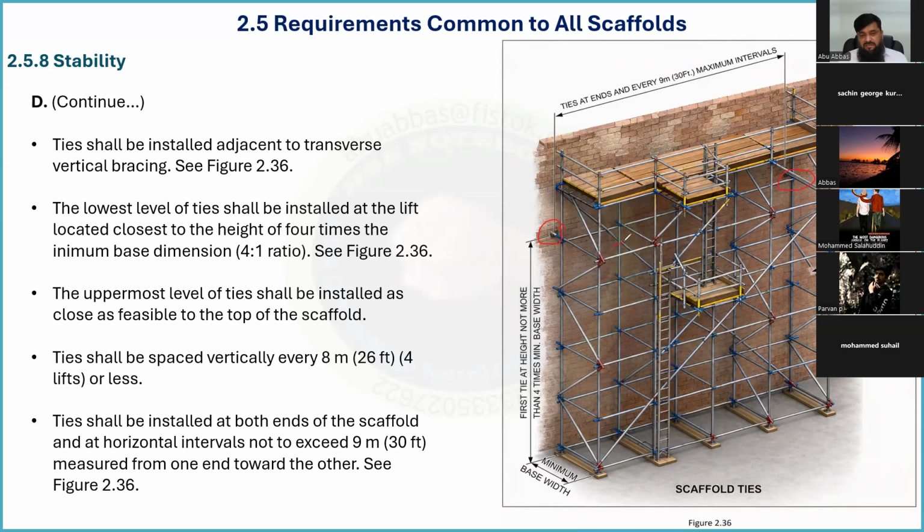For example, let us say it's 2 plus, and almost here, we can bring it closer. Now, in this situation, we have reasonably less distance. It's not 9 meter if we go beyond this. So it's better we come lesser than 9 and we put it near the node point, where the vertical and horizontal members come together.